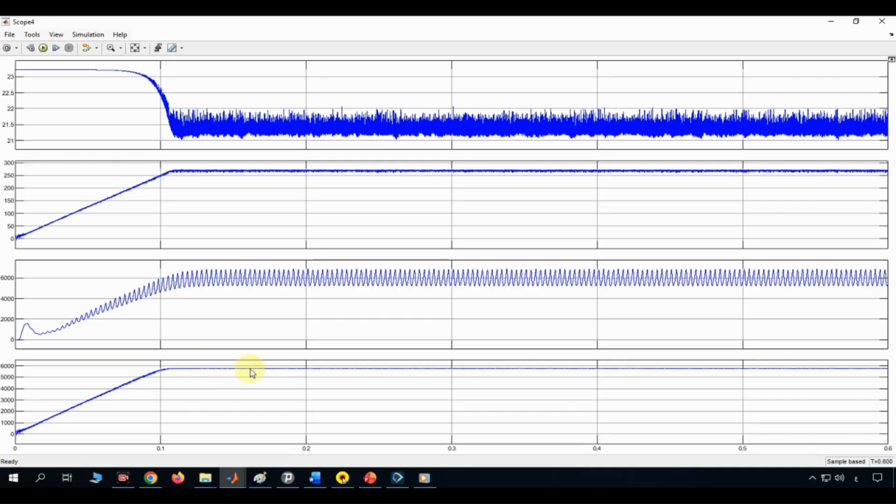So, reading all four traces together, in the first tenth of a second, the system is starting up, voltage ramping smoothly toward its target, current settling down from an initially high value, and power climbing with growing oscillations as both of those settle. After that startup window, the system reaches a steady operating condition, a fixed voltage, a fixed average current, and a power level that oscillates around 5,000 due to switching ripple, tracking closely underneath a smoother reference power level just above 6,000.